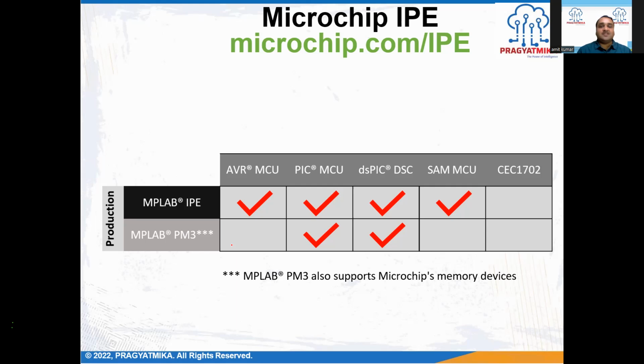So what we have is the MPLAB PM3 approach, where there are dedicated programmers on which the microcontrollers are put in an array, and all of these microcontrollers are programmed at a time, maybe 100 microcontrollers in the PM3 environment. So for memory device programming or array programming of microcontrollers, we use the PM3 environment. If it is individual microcontroller programming, then the IPE approach is there.